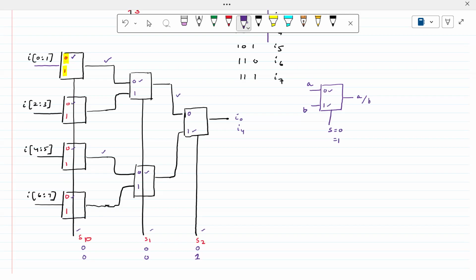So now what is the modification that you can do here? Where should the MSB be then, and where is the LSB now? If you keep it like this, for example, S0 here, S3 here, then what will happen? The first case is anyway okay, I0 will come.